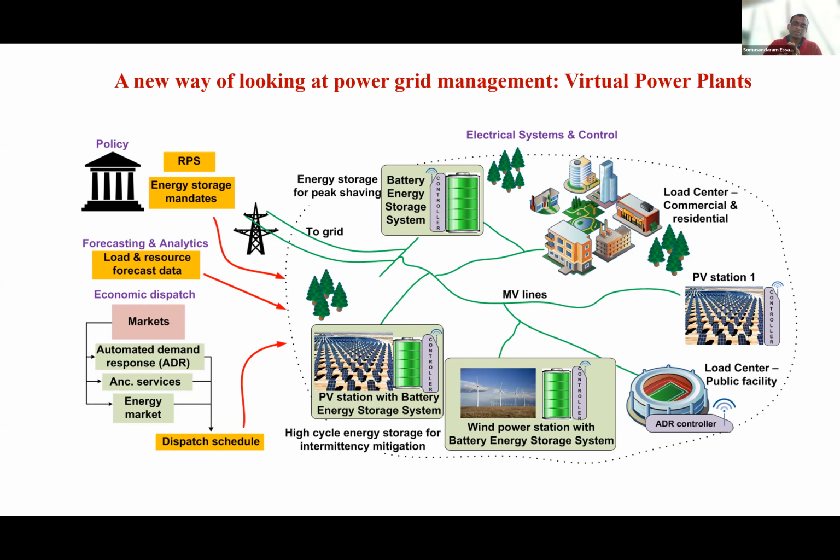And then, like I said, depending on the ratings of the power plants, a dispatch schedule is created whereby they say, well, at this time tomorrow, power station 1 generate this much, power station 2 generate this much. And this is, like I said, a negotiated agreement that happens between generators and grid operators, right? So that is what this picture is trying to capture.